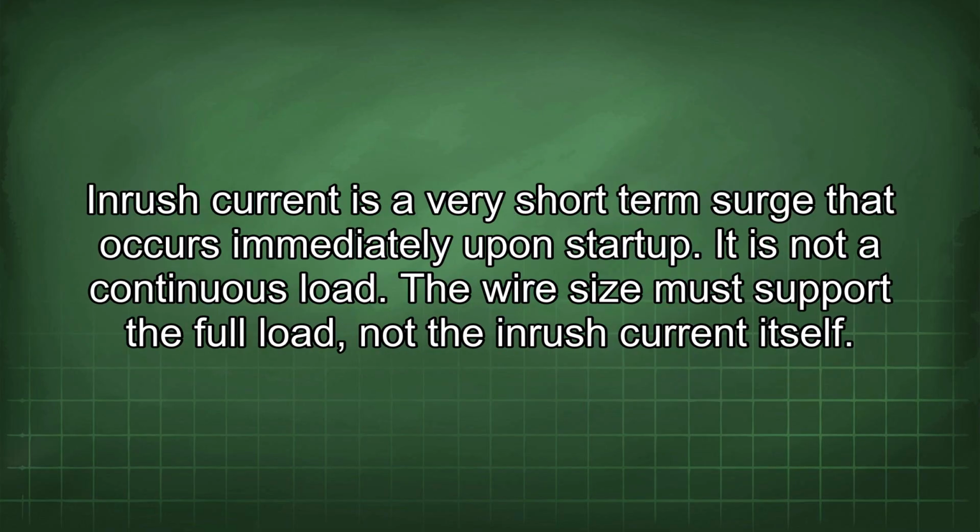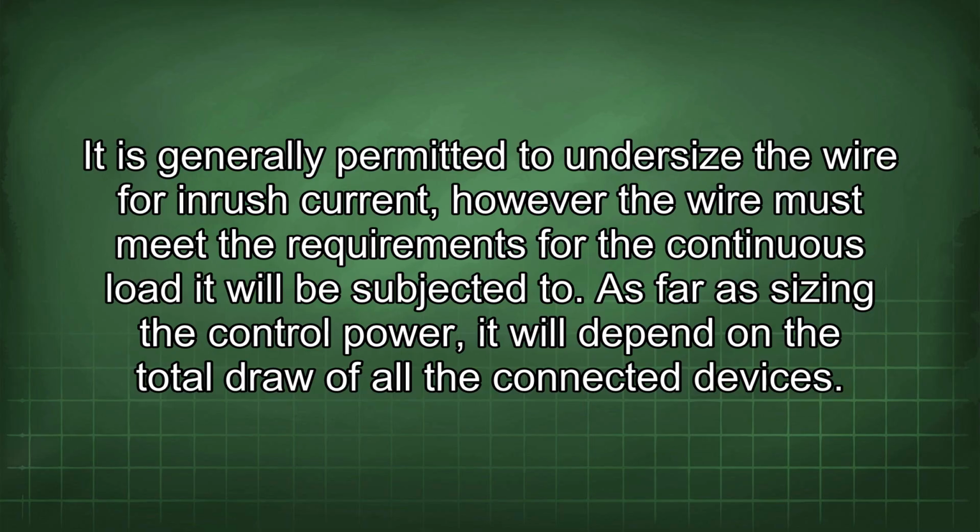Inrush current is a very short-term surge that occurs immediately upon startup. It is not a continuous load. The wire size must support the full load, not the inrush current itself. It is generally permitted to undersize the wire for inrush current, however the wire must meet the requirements for the continuous load it will be subjected to.